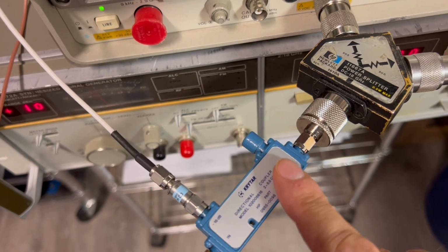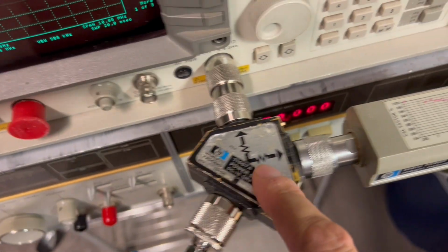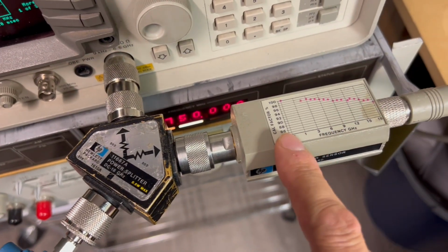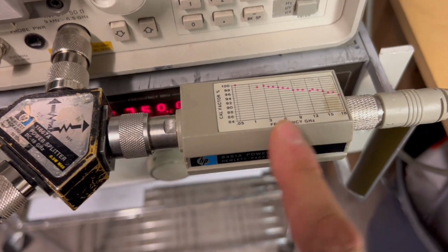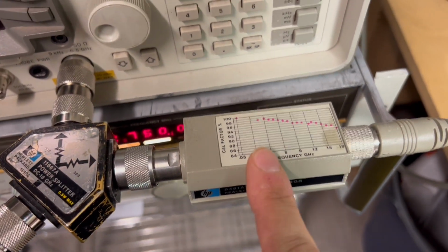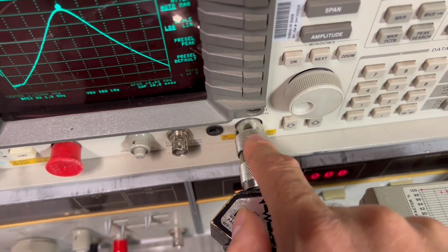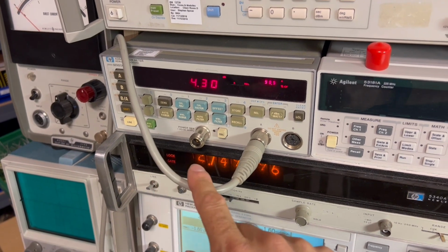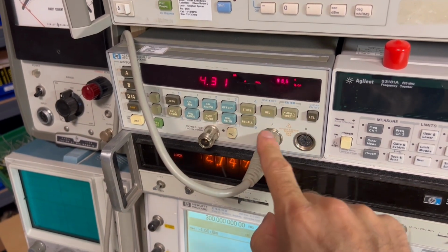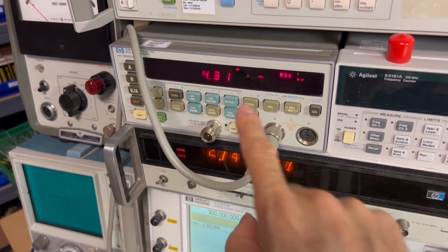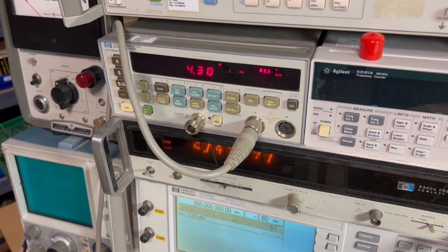And anyway, from the coupler, it's going to go into a power splitter. We've got the HP 8481 power sensor set up here on the output of this port, and the other port going to the spectrum analyzer. And we're taking the relative power reading here for our first measurement. See, we're getting a 4.3 dB relative measurement there.